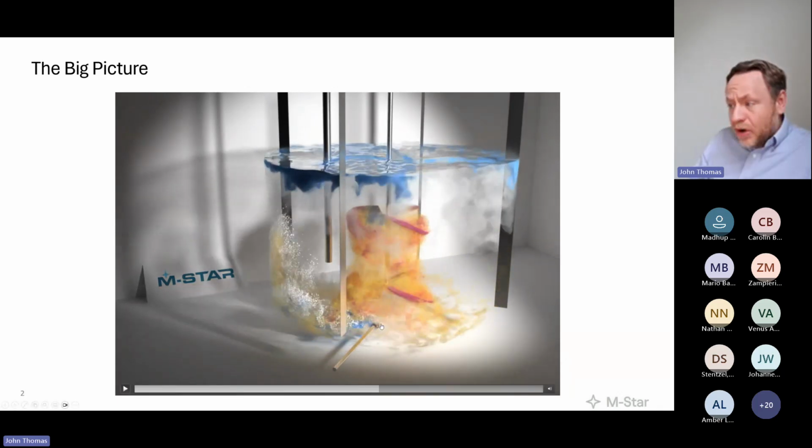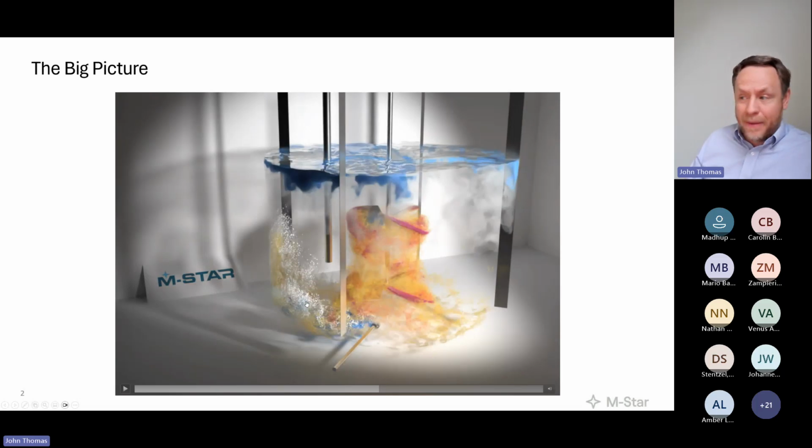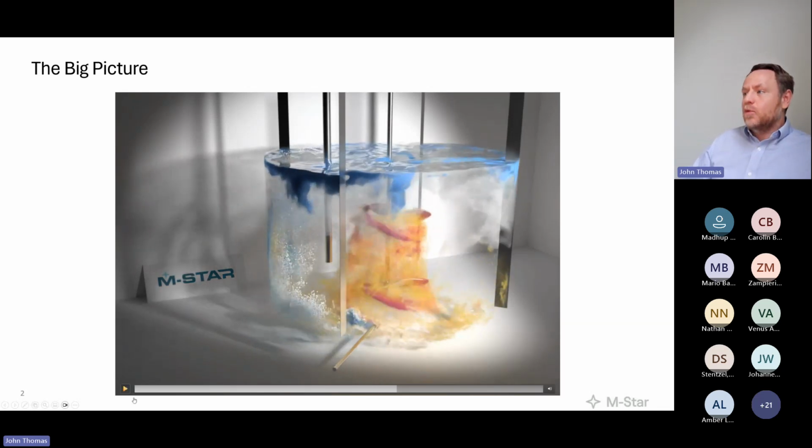Now, when we sparge gas into the system, we have another oxygen or dissolved gas transport mechanism. We have KL and individual mass transport processes going on around each individual bubble. These are also pouring dissolved oxygen into the batch here. So we have two paths. One is the headspace and transfer via the interface. One is the sparged gas.